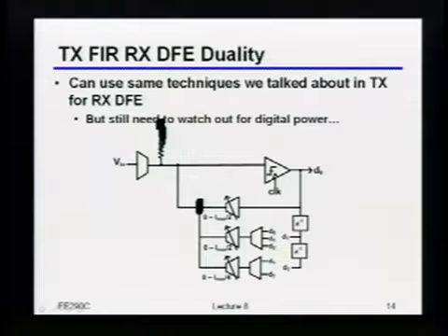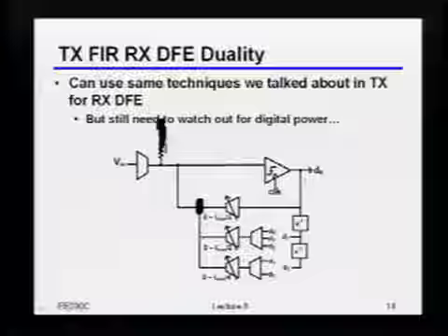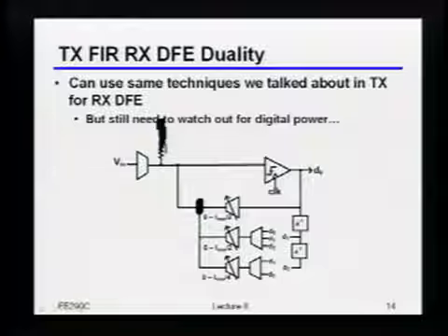So don't get me wrong, you can do all the peaking, you can do all the high bandwidth tricks that you'd like to do. I will mention, however, that the inductor will probably be 5 to 10x larger than the rest of the circuit. But yes, you can absolutely play those tricks. I'm not opposed to it. I'm only saying that unless you're really pushing on the speed, that tends to be just expensive from an area standpoint. Other questions on this?